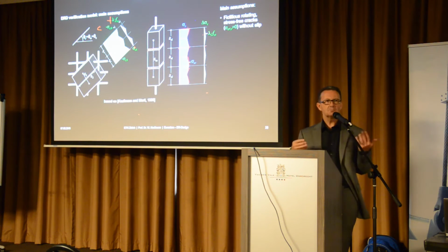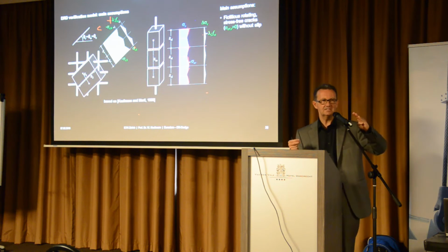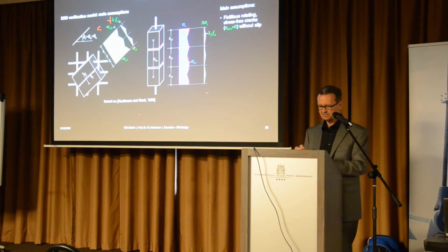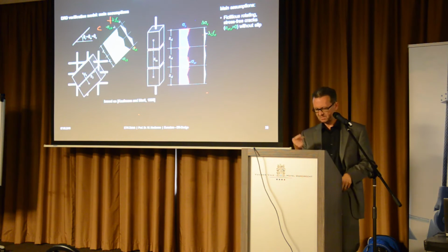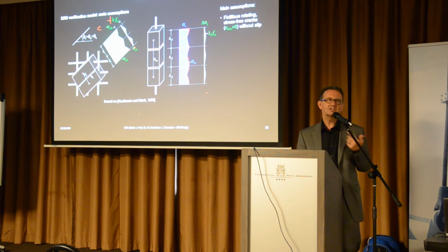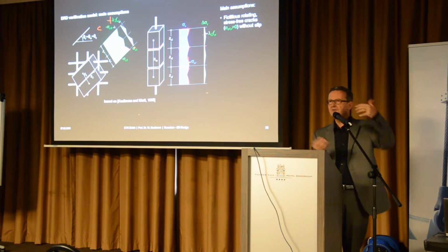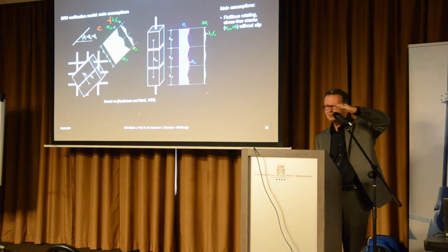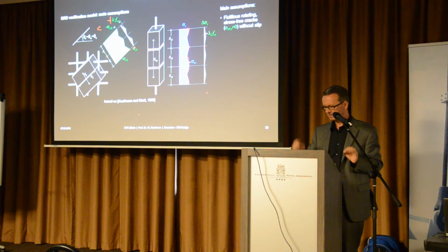For non-isotropic reinforcement, the principal directions will also rotate slightly between the crack. So that's not entirely 100% consistent, but maybe 99.9. We have done these calculations, it's very little. Because bond stresses are not the same in two directions, cracks are flatter than 45 degrees, and then one direction gets more tension stiffening than the other.